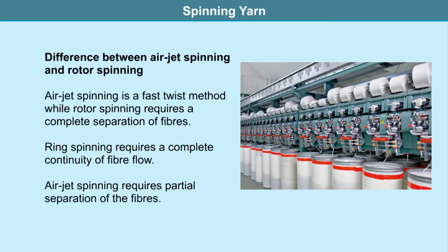Similar to rotor spinning, the input strand in air jet spinning is a drawn sliver that may be carded or combed. Drafting is achieved using high roller drafting to reduce the size of the input sliver to the desired yarn size. The binding mechanism is achieved by blowing compressed air through two nozzles to form an air vortex. One is the end opening nozzle and the other the twisting nozzle. The yarns produced are twisted in one direction.